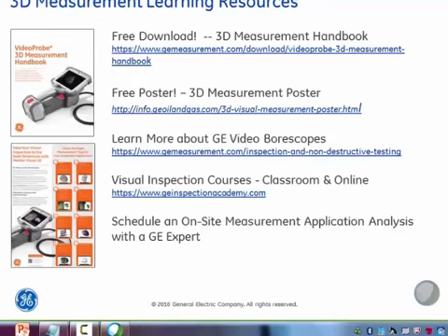It may be also worth trying 3D stereo at some point, which sometimes will give you a little better performance in those highly reflective applications. But again, with stereo, the thing that gives you the most trouble is glare in the image, which again can happen with a perpendicular viewing perspective. So off perpendicular views tend to help you with both technologies.